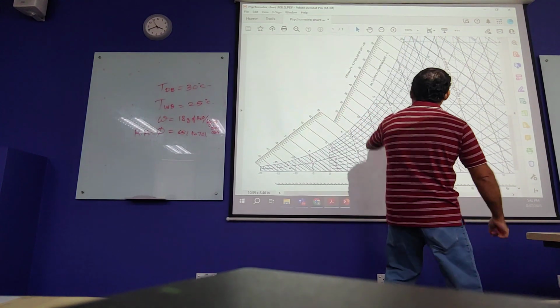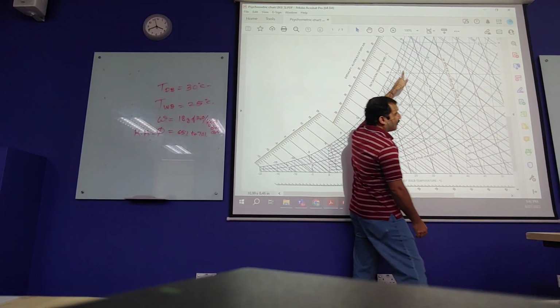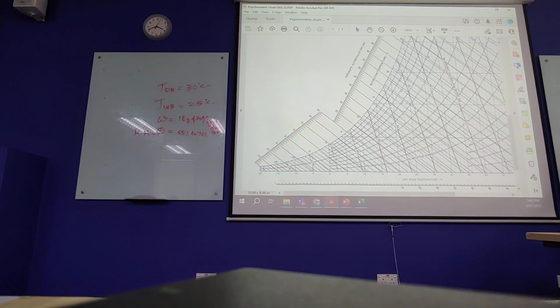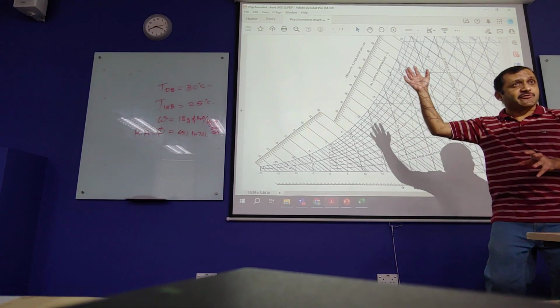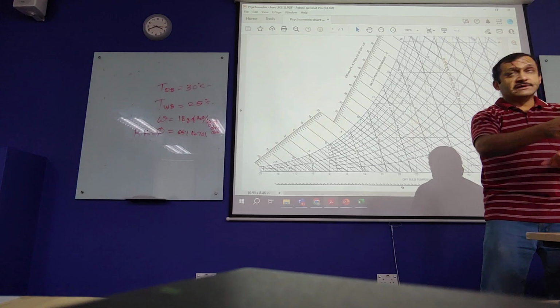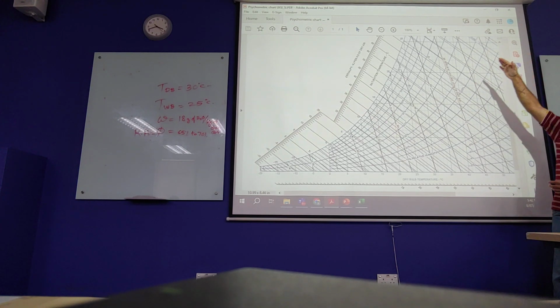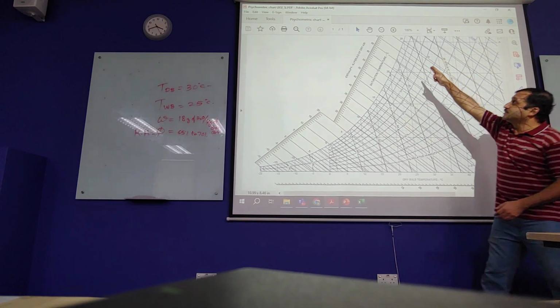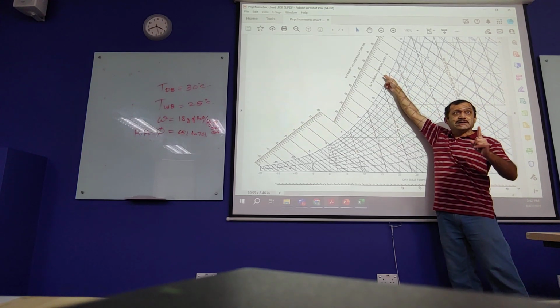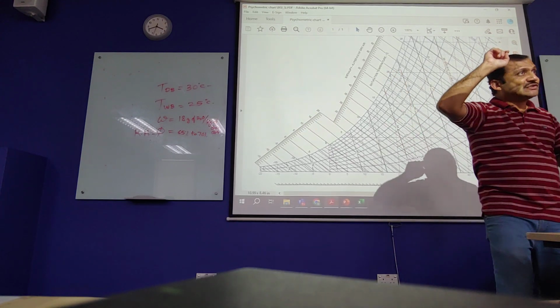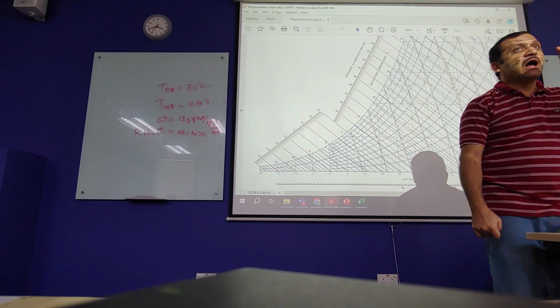But what will be its relative humidity? So you reach 20. So what's going to happen? The process will look like it goes from there, horizontal, and then continues following that curve and reaches 20. And that's where we are at the moment. We have cooled down the air from 30 to 25. In turn, we have removed some moisture. So originally there was a certain amount of moisture. We have cooled it down and removed some of the moisture from the air just by cooling it. But our target is not relative humidity of 100%. We want relative humidity of 60%. So what are you going to do next?